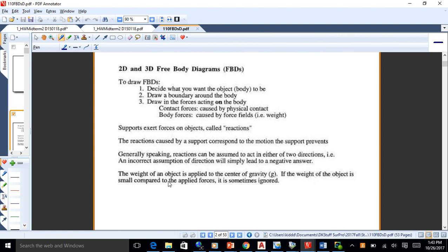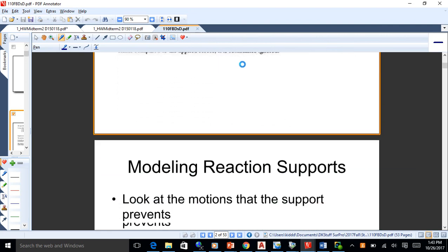All right, now we've got two different types of forces. We've got actions, which are the applied forces, which we've been looking at here so far, but we also have things that support the object, usually by physical contact, and they're called reactions. The forces at these supports are called reactions. Once you know the actions and the reactions, you know all the forces acting on the object. Once you know that, you can start to work to design it so it can withstand those forces.